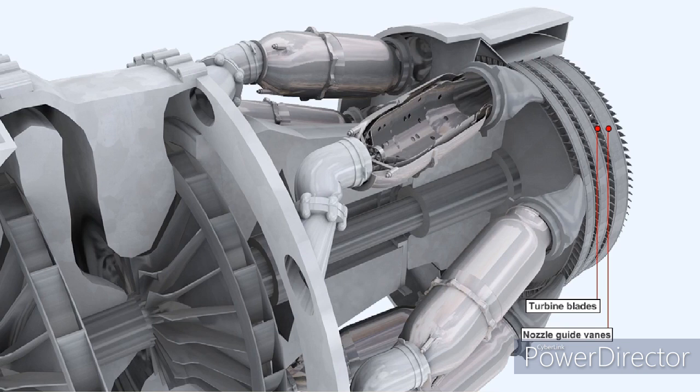The Germans' inability to produce materials which could withstand the heat of the gas stream was the main problem with the early German gas turbine engines. Because of the poor materials used in the turbine assemblies, the engines would only run for between 10 to 20 hours before the turbine blades suffered meltdown and engine disintegration commenced, usually in a quite catastrophic fashion.